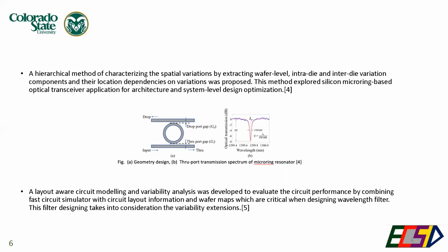The next paper that we have referred to is a hierarchical method of characterizing the spatial variations by extracting the wafer-level, intra-die and inter-die variation components and their location dependencies. This method was explored on silicon micro-ring based optical transceivers for architectural and system-level design optimization.